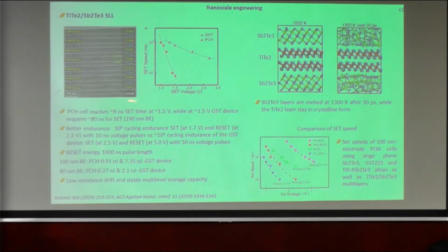and for GST we know already it's like 80 nanoseconds, of course depending on the device geometry and material parameters. Also, such a stack has a nice endurance, it can operate up to 10 to the 9 cycles, and the reset time at the reset voltage is like 10 nanoseconds.